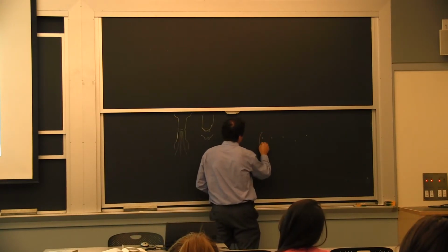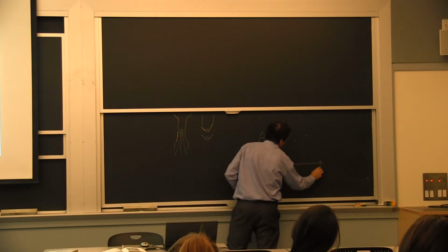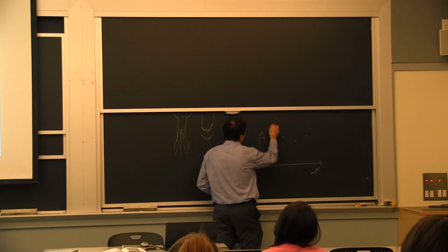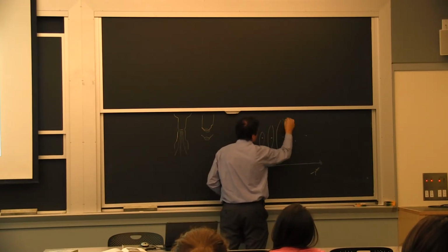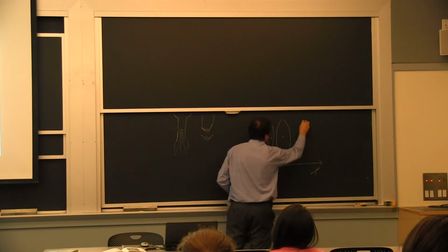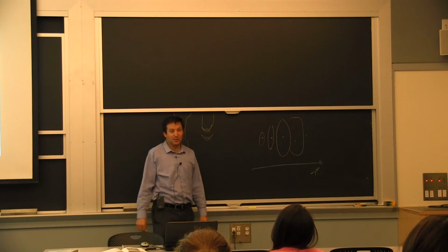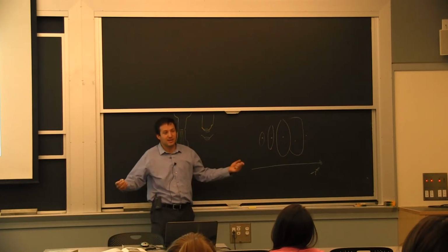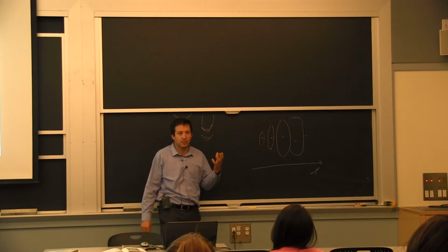So what happens with the voids, I'm going to draw it as a function of time here. So over time, they'll stretch and stretch, and they become a little wider. And then you get to a condition where they'll touch each other. And there's no material anymore. It's a crack that you just formed. And you have to think about it in 3 dimensions.